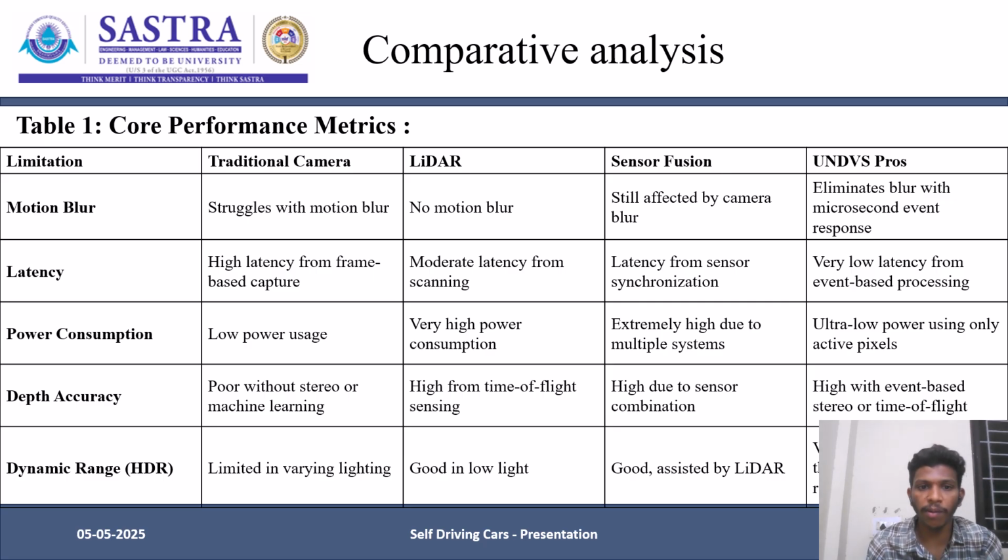And this is the core performance metrics of the traditional camera, lidar, sensor fusion, and the unified neuromorphic depth vision sensor. The limitations of these three technologies will be overcome by the UNDVS. Motion blur, which is a struggle for the camera and lidar, is eliminated by the UNDVS with its microsecond event response.